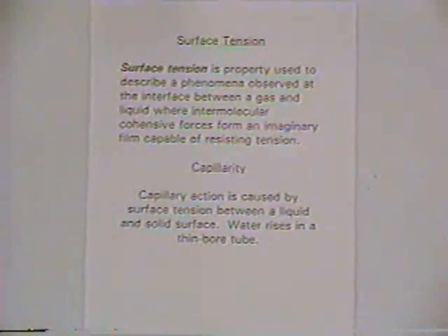And a related phenomenon is capillary action, and that's caused by the surface tension between a liquid and a solid surface. You usually picture that as a thin bore tube. Water will rise up in the tube as the liquid adheres to the sides of the tube. Or in the earth, in geologic groundwater aquifer formations, where you've got sand and gravel and a water table, the water will rise up in the little porous media between the sand and soil particles due to capillary action.